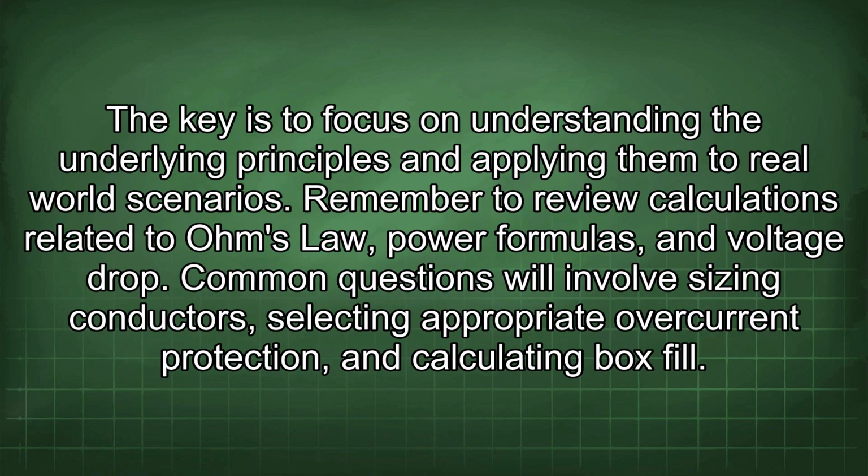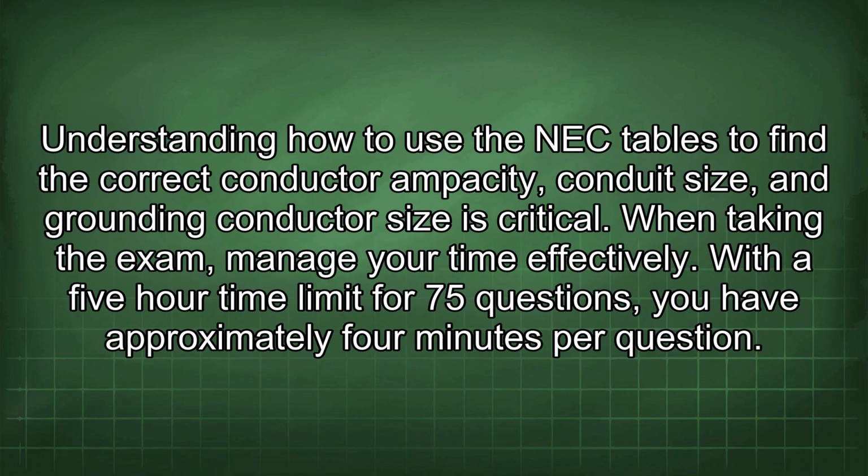The key is to focus on understanding the underlying principles and applying them to real-world scenarios. Remember to review calculations related to Ohm's law, power formulas, and voltage drop. Common questions will involve sizing conductors, selecting appropriate overcurrent protection, and calculating box fill. Understanding how to use the NEC tables to find the correct conductor ampacity, conduit size, and grounding conductor size is critical.